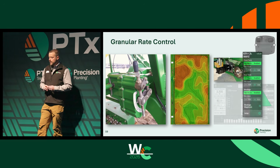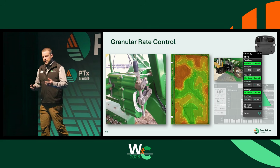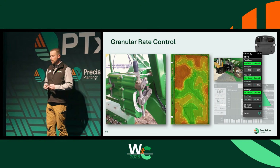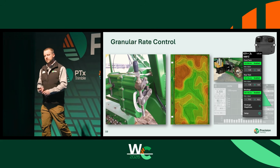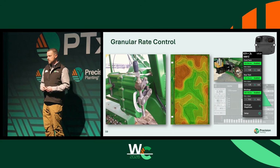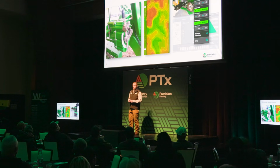Now, if I put a 2020 in the cab for Clarity, very simply, I can add to it a rate module. I can add a seeding motor. We offer the brackets and all the sprockets and all the parts to add this motor to my cart. So I can convert from ground drive control to a hydraulic drive. When I convert to that, then applying that prescription, executing those rate changes is going to be a lot easier because I make that change through the cab. I calibrate through the 2020, so now I'm monitoring and I'm controlling all in the same screen.